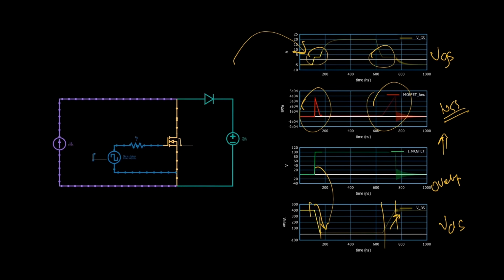It's pretty unnatural, isn't it? I mean, during this entire time, the gate driver has applied 20 volts to the MOSFET, and instead of rising suddenly, for some duration of time the VGS has chosen to stay flat. That's the plateau. Why it occurs can be treated like a mysterious characteristic of a mysterious device, that's the MOSFET.